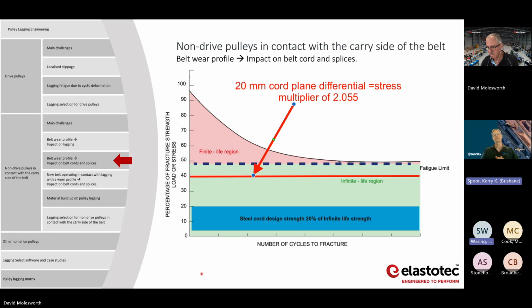I think Stoney was in the conversation too. We've all seen on site, or at least I've seen it particularly on tail transitions, returning back to a single V. You see, as it's approaching the V plow, supposed to be way past the transition, you've still got residual tension stress and that seagulling effect on the belt. So I'm not buying it, Sean. I still think there'd be some still there. It's just the safety factors that they try to make the length so that the safety factor is not exceeded in that zone for the belt.